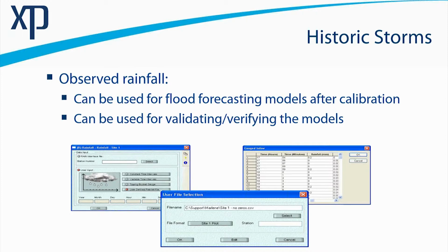We definitely need sub-daily time steps. Ideally, you would want to obtain the raw rainfall data to allow an appropriate study to be undertaken. Taking daily values simply distorts your ability to analyse a catchment, because you'll have to assume the rainfall occurred consistently over the day, whereas we know that rainfall spikes in sometimes very brief periods, either 5 or 30-minute periods. So daily historic data is inadequate, and if you're able to procure sub-daily values, or again that raw information, when did the rain gauge tell us that it received a millimetre of rain, that would be a much better data set to analyse.